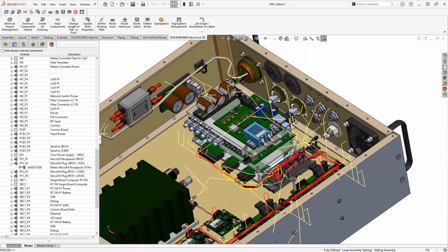You don't have to go to this extreme with it. If it's Panduit, and you're doing a cabinet and it's essentially a figure 8 position, you've got a top row, there's one in the middle and one on the bottom, and a couple side rails too. That's all you need. You need a line. It's just a 3D sketch line to tell the wires that I want you to follow this path.